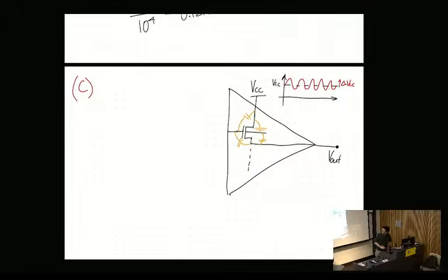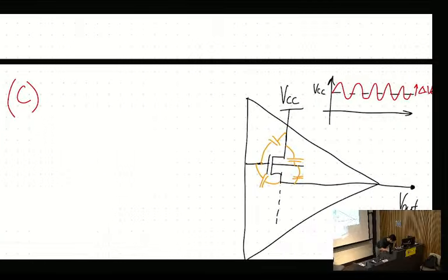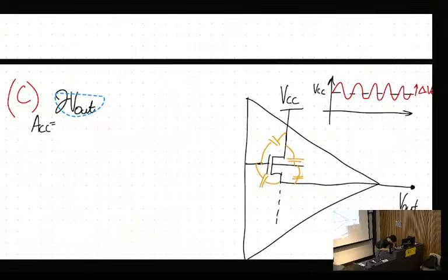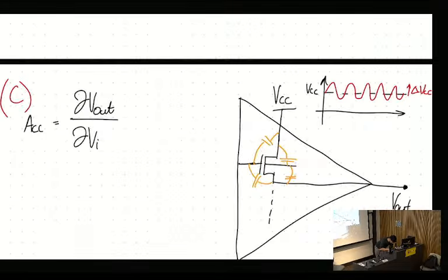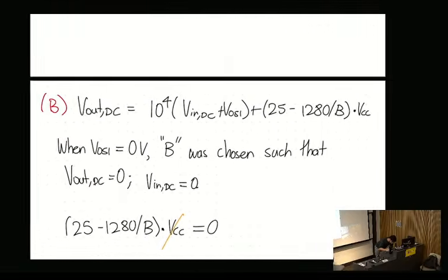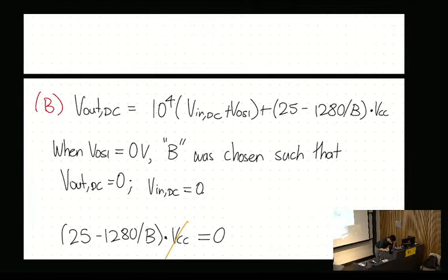Okay. So parasitic capacitance and its gain. So now we need to calculate the ripple. So we know that the power supply gain is dV out on dV in. So we're given a formula which is on VCC, because VCC is our new input. And so if I go back to this equation here, now instead of treating this as just some constant signal, now I'm treating this as sort of VCC as a time domain signal.